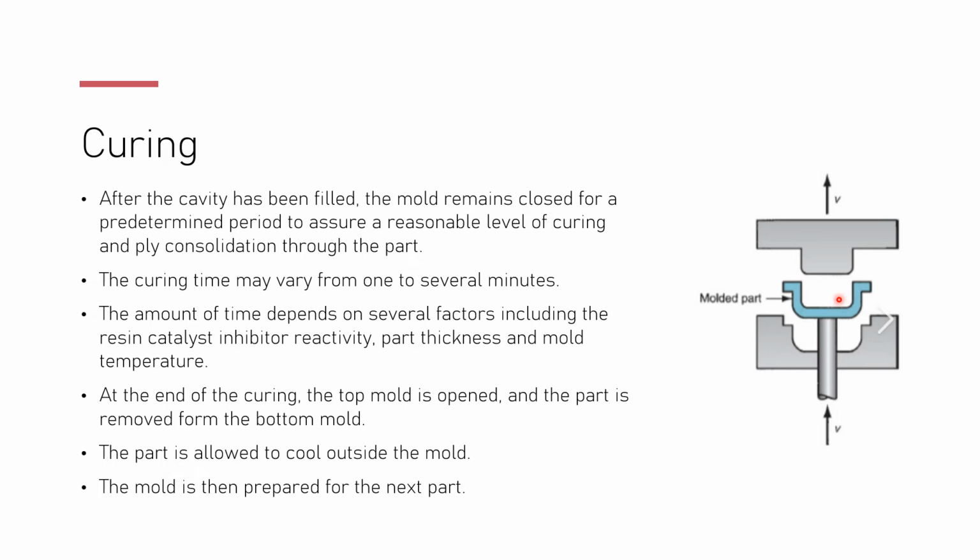So why do we have to do it? We want to maintain the quality of the product. This step is so important in quality assurance. The curing time may vary from 1 to several minutes. The amount of time depends on several factors, including the resin catalyst, inhibitor reactivity, part thickness, and mold temperature.